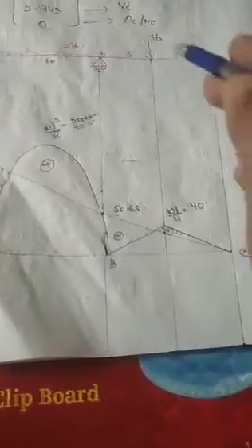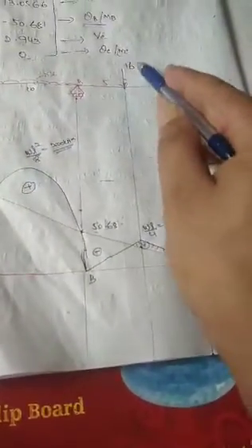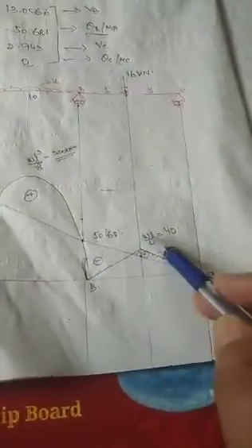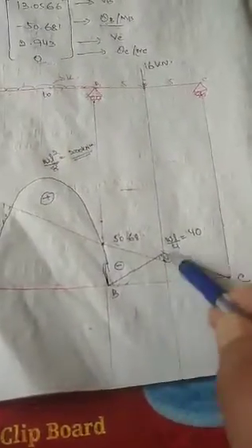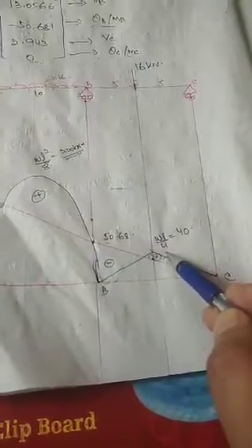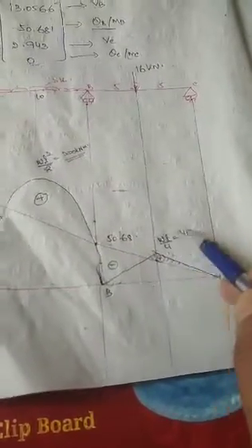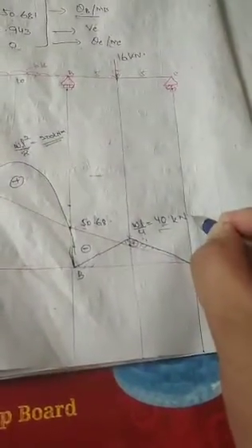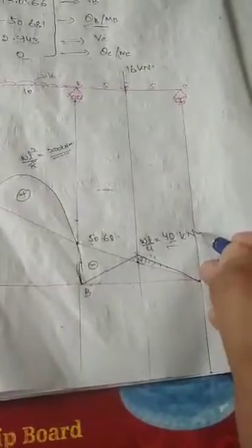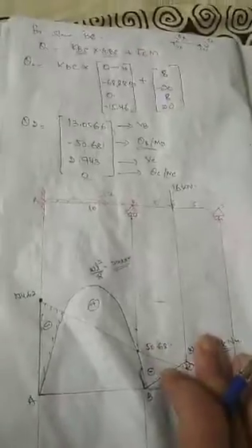Then second, for this point load, it is 16 kilonewton. For 16 kilonewton, you have to draw the bending moment diagram. WL by 4, it will be a triangle. Yes, it will be a triangle. WL by 4. On applying the value of W and L, you will get 40 kilonewton meter value. So this was the direct stiffness matrix method.